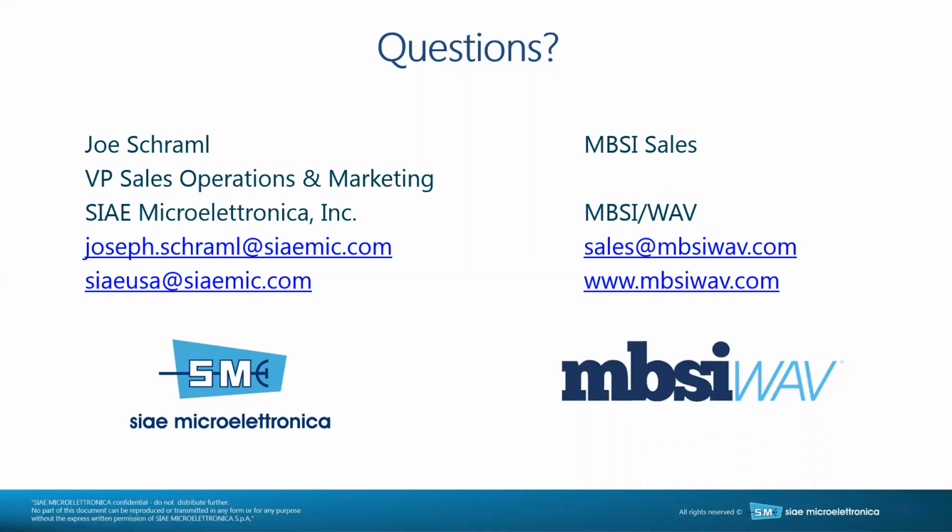So I think, Cody, with that, I'm going to turn it over. We get some questions here. I think the first one here is whether the PoE is 802.3af or 802.3at. It's neither. These radios consume more power than, say, an AF device. The ALFOplus2 radio itself has about 75 watt power consumption.